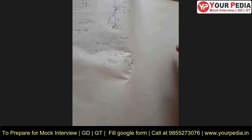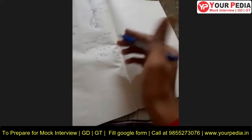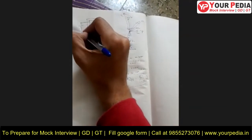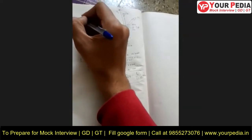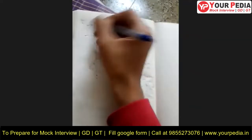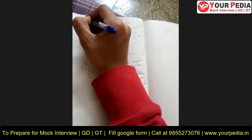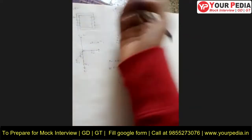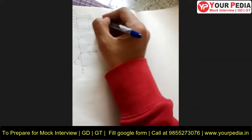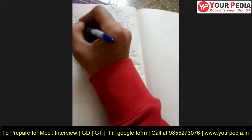If suppose we apply DC to the primary of a transformer, then what would happen? That depends upon the amount of DC voltage you are giving, sir. Mostly the current would be VDC by R1, sir, the resistance of the winding. If this current is greater than full load, then the windings may get burned. If it is less than full load, no voltage will come on the secondary, and literally it will be a short circuit, sir. Just current will be flowing. That's it.